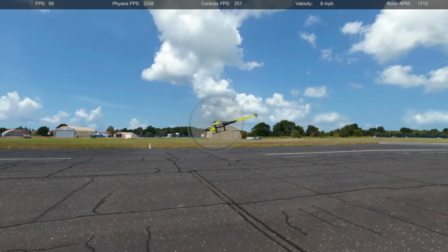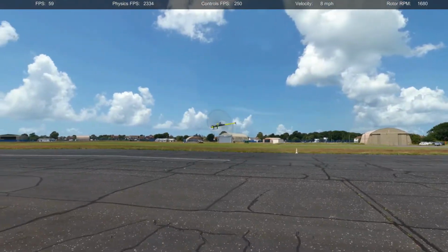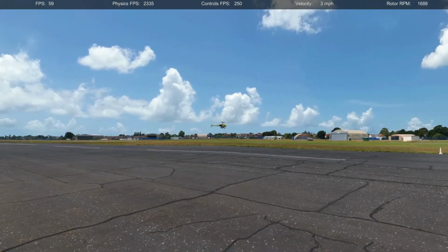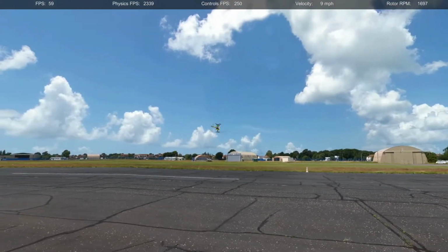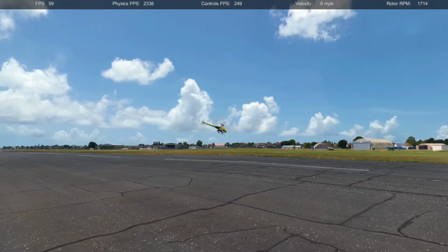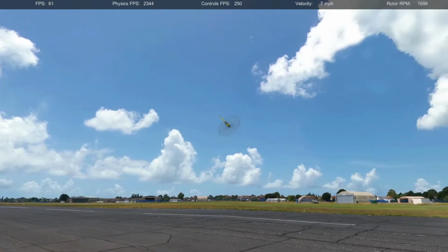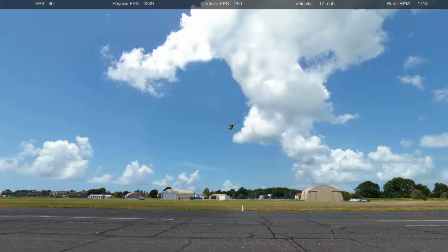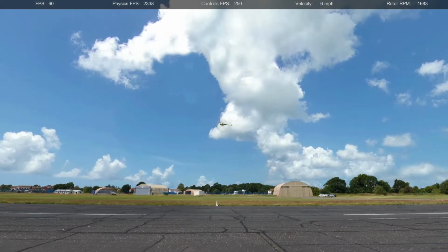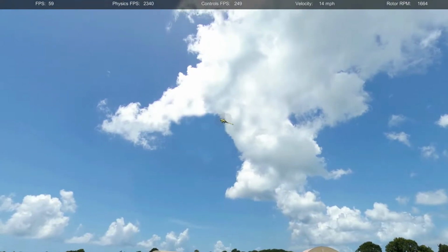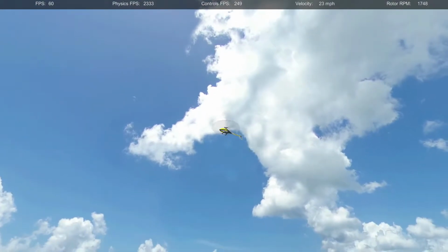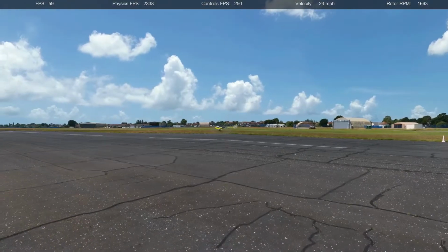So here's what we get. Downwash in the middle, you see the upwash at the tip on each end. In fact, if you could see the vortex and the wake, now remember, this is not real flow. This is just math, right? On a computer screen, it would look something like that. So you can see that the vortices are not at the wingtips. They're about 70% of the way out.